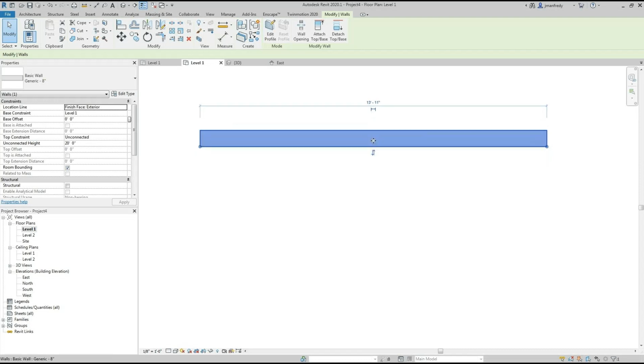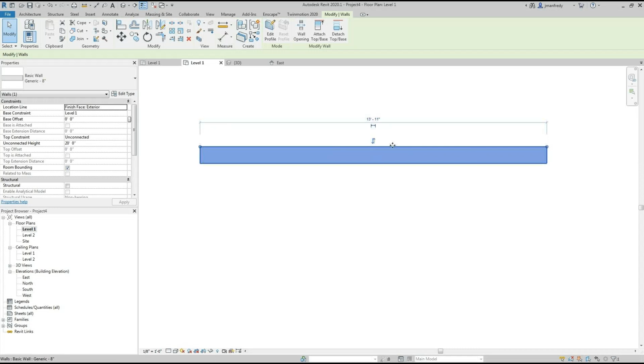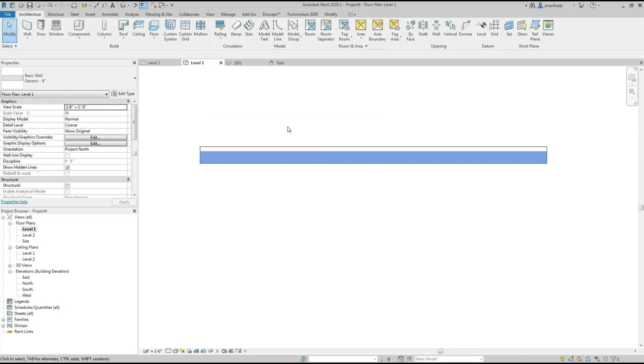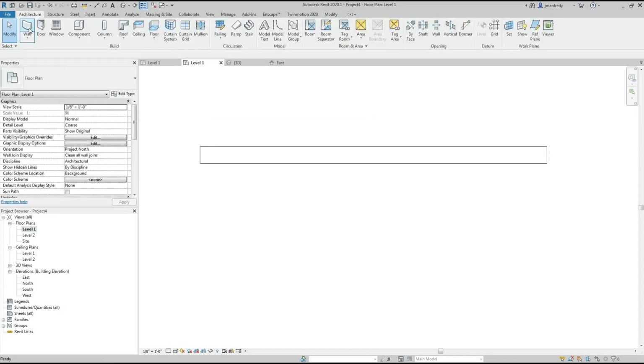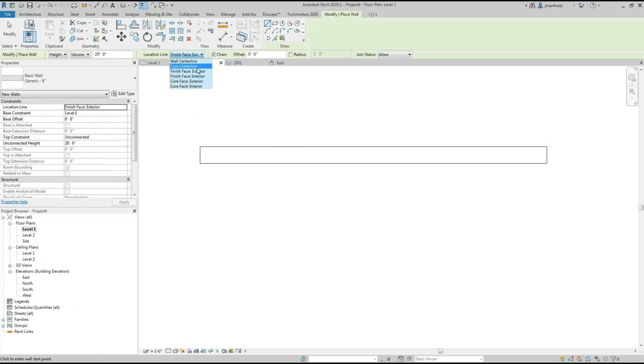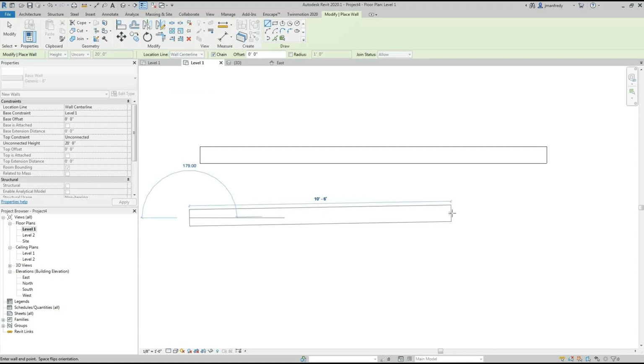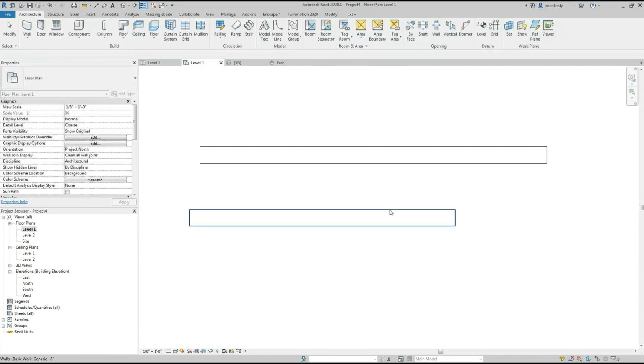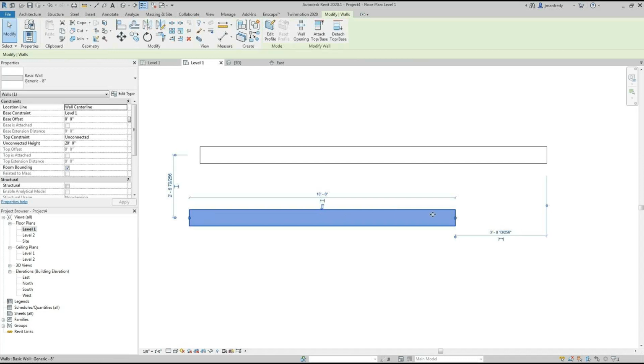That arrow lets you flip the edge of the exterior, see? Because I drew it there along that edge. So you have the choice when you do the wall command to draw a line from the exterior face or the interior face. Now the core we'll talk about later, that's different. And the wall center line is obvious. When I drew a center line, you see the dotted line? That's the center of the wall. So it doesn't matter if you flip this. The center of the wall is maintained, and the exterior will flip over to this side. But the wall didn't move because the center was used.